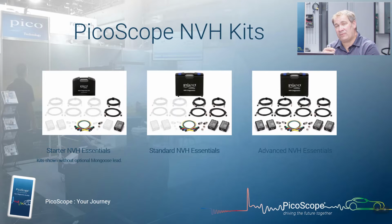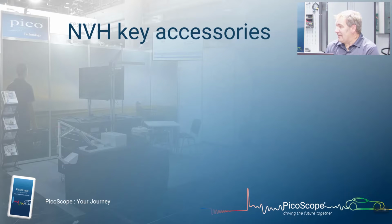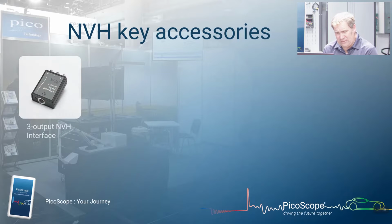And as we start to run through how we connect to the vehicle and certainly how we start to try and pinpoint NVH issues, you are going to find only having one accelerometer a real restriction. So it is worth, if you can, and it does work out better, more cost effective actually, to buy the standard kit as opposed to having the starter kit and then adding on components. And of course, if you can, the advanced kit does give you a huge amount of options when it comes to testing.